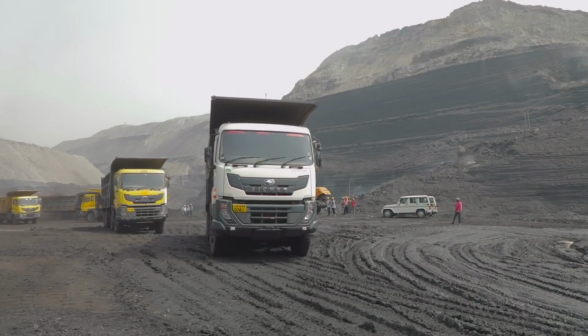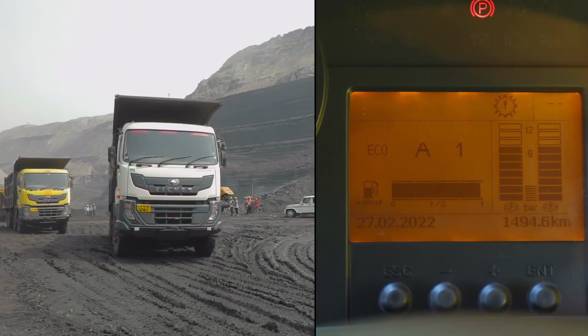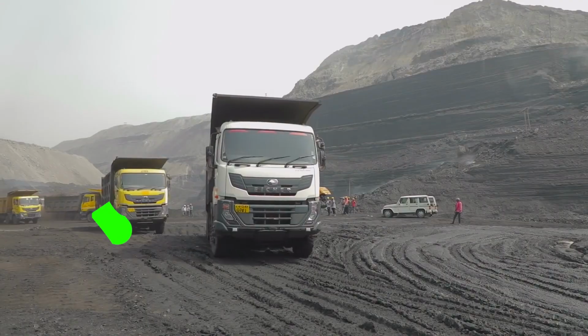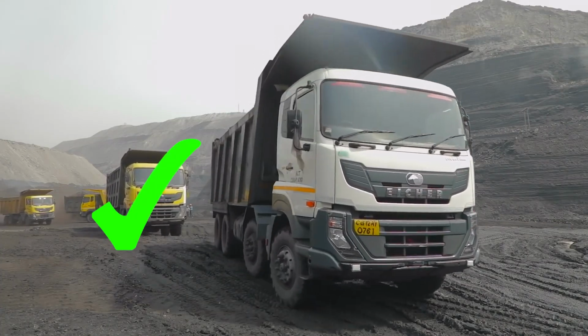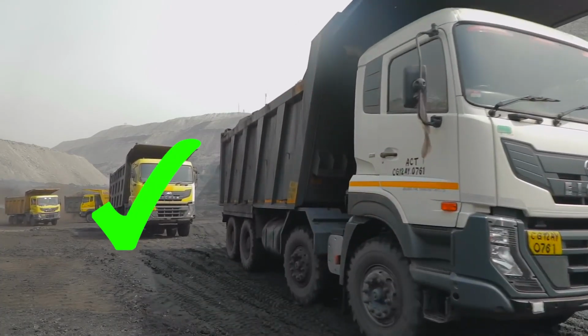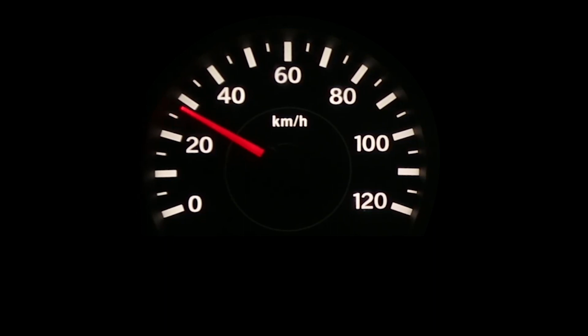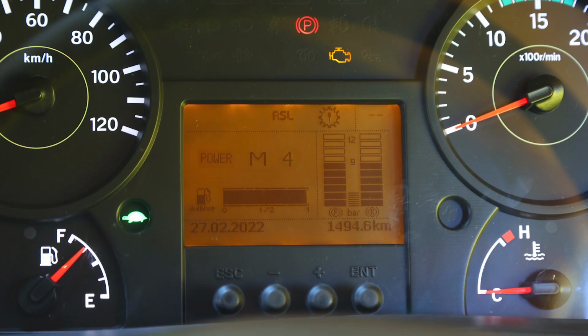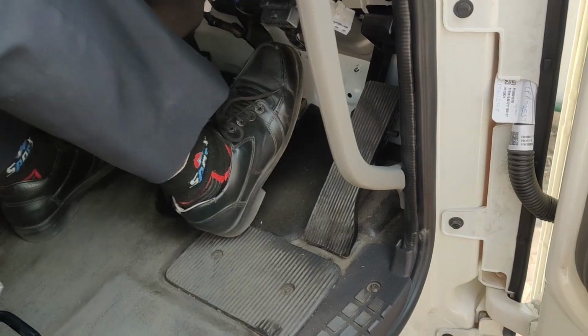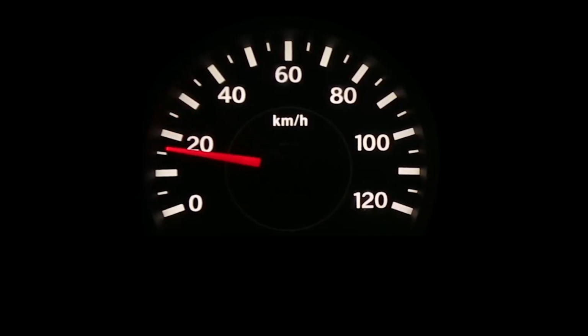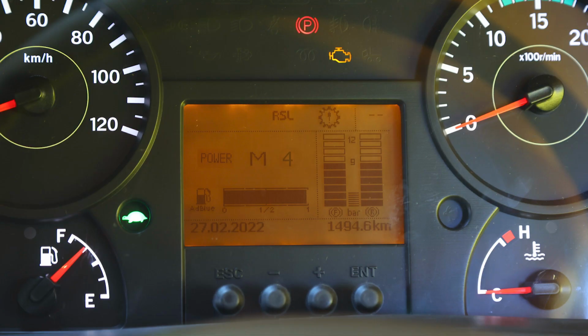While overtaking in automatic mode, press the accelerator pedal fully for getting desired torque and speed. This is called the kick-down feature. In this, lower gear shifting takes place for increasing speed and torque. This feature will provide more pickup. If the vehicle is in a higher gear and a sudden brake is applied, vehicle speed 0, then the gear automatically comes to crawler or first gear.